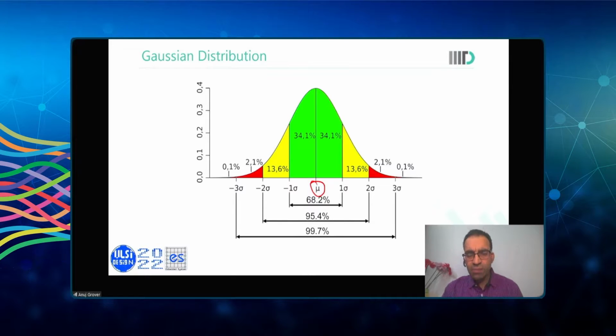Let us just put in some numbers. If I say that the typical on-chip SRAM capacity on a chip is 1 megabit. Now 1 megabit is too small. In advanced technologies like 7 FinFET or 14 FinFET, you would already see that a typical digital SoC would have an on-chip memory which is greater than 32 megabit or 64 megabit. But for now let's just assume that we have 1 megabit on-chip capacity.